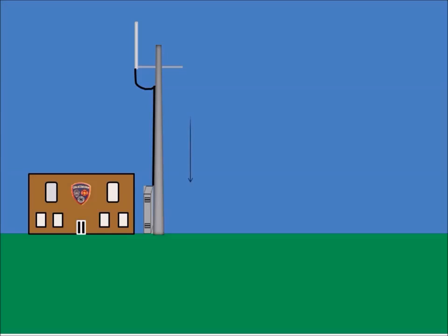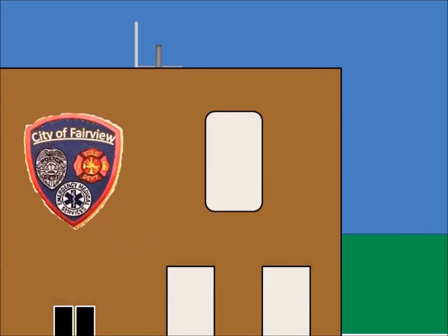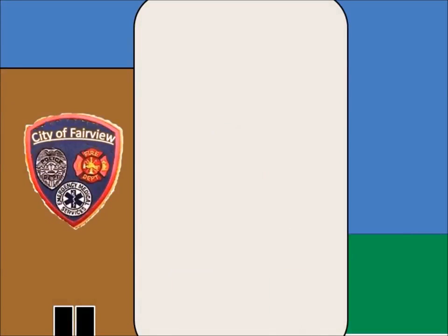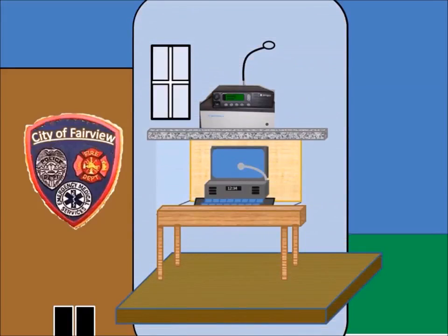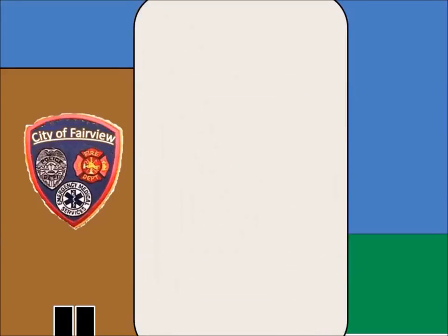This coaxial cable has a radio signal loss and should be kept as short as possible, which is why a base station is usually not too far from the antenna. The base station may be directly located at the dispatcher position, with the antenna connected to the base station. Small stations, generally known as control stations, are many times used for this purpose.